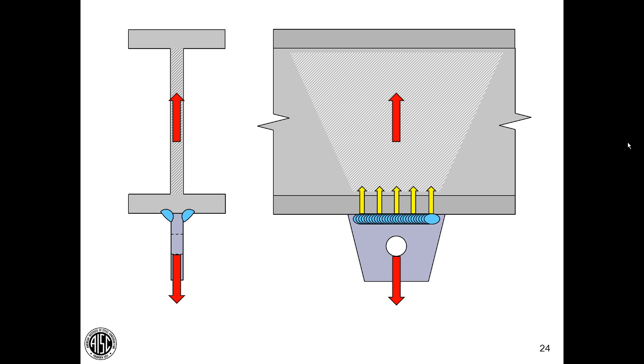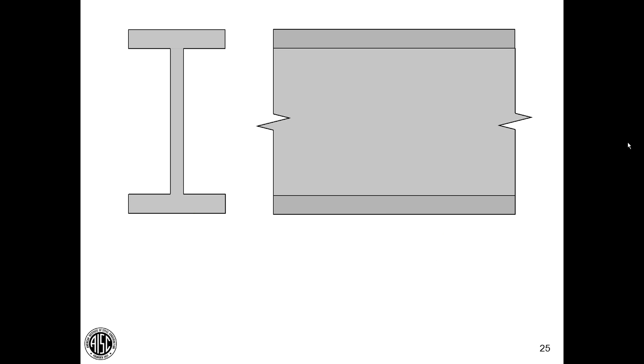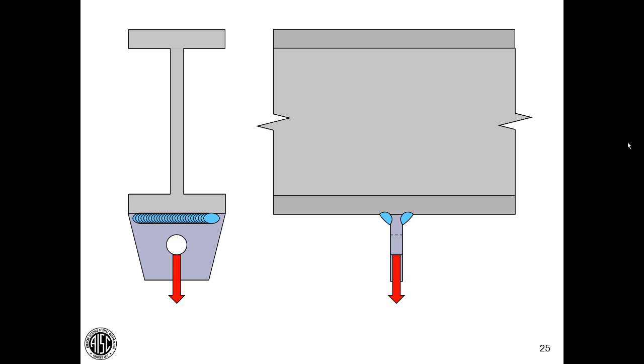Let's rotate that lug 90 degrees. We won't change the lug, it's the same. We don't change the weld, we don't change the beam, we don't change the load. But our load path now is totally different. The force still wants to enter into the member that lies parallel. But do you see that the weld is no longer uniformly loaded along its length? We have a peak stress in the middle of the length of the weld.